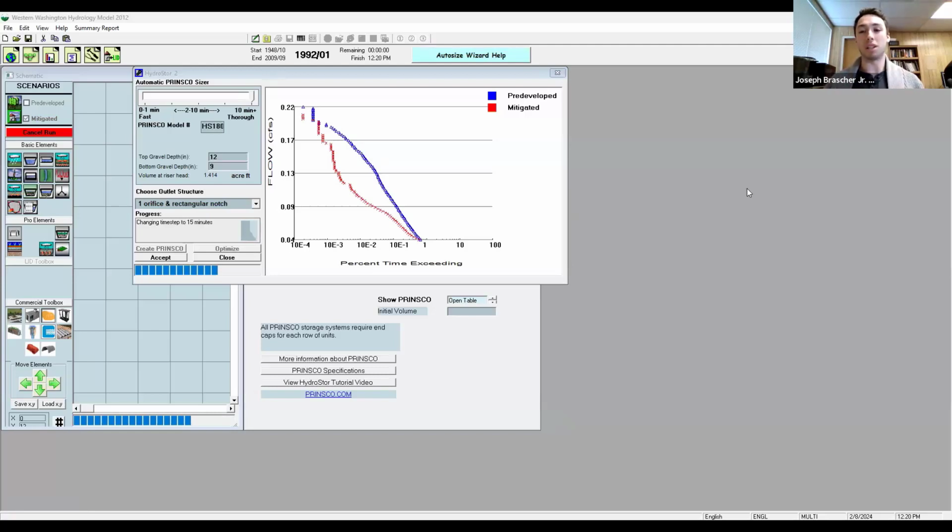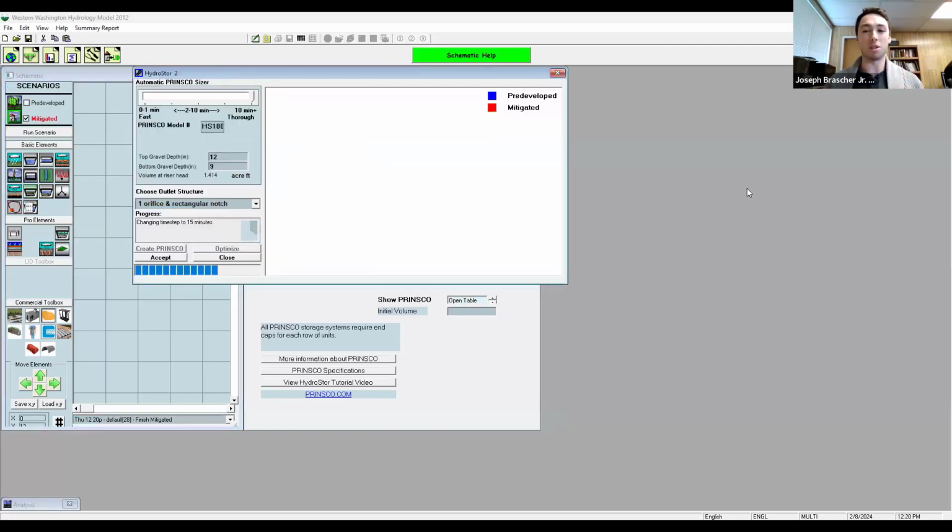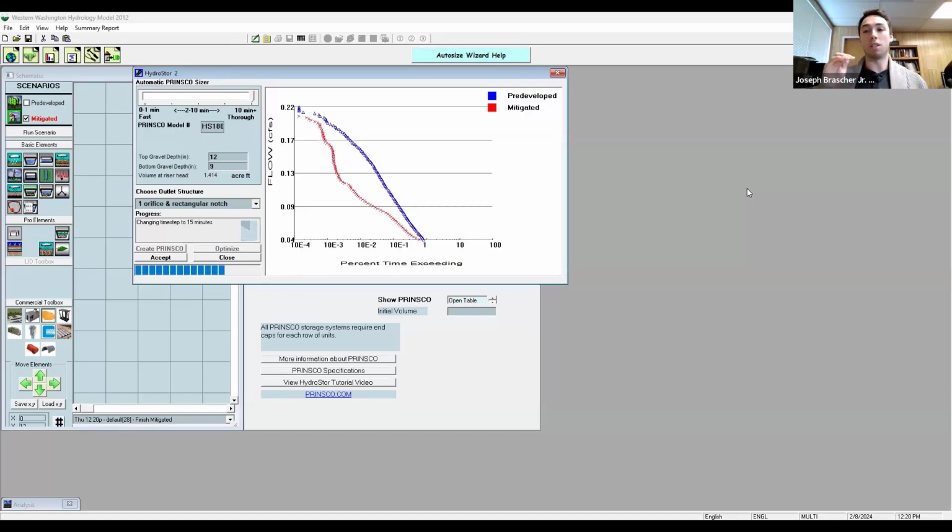And that's why continuous simulation is needed. He corrected it to impervious. I'm sorry about that. So, different runoff coefficients associated with impervious. For impervious areas, they're basically all the same for the different slope categories. But when people submit projects or organize their projects, they like to have the different kinds of impervious areas, which I totally understand. So for example, sidewalks flat and roads flat are the same impervious area. You could put in 10 acres of roads flat and have that mean 10 acres of sidewalks flat.